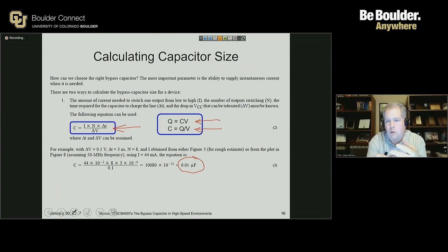So that's the first gut check that you would have. Another thing that you could do is measure in your circuit. This is something I haven't gotten to yet, but one thing that sometimes system designers will do is put placeholders in their circuit. They may say, I need decoupling capacitance in my circuit, but I'm not sure exactly how much. So in the design, they put a whole bunch of capacitors close to each chip where it's needed. And then once they get their prototype boards back, they optimize their circuit based on actual functionality.